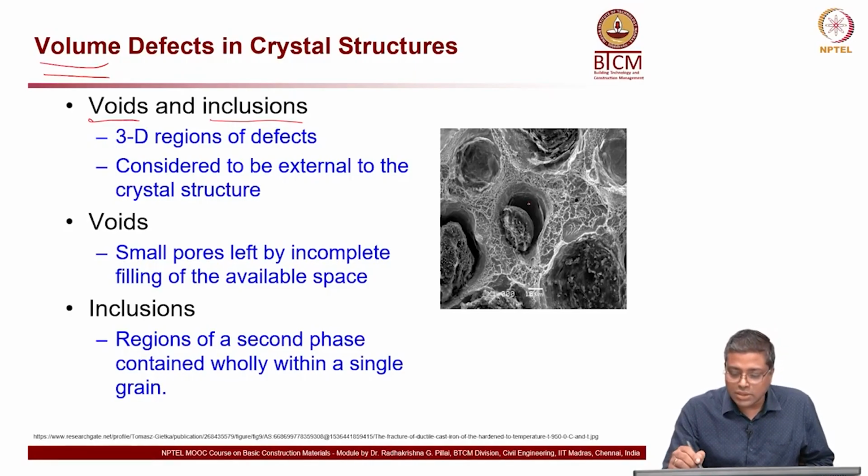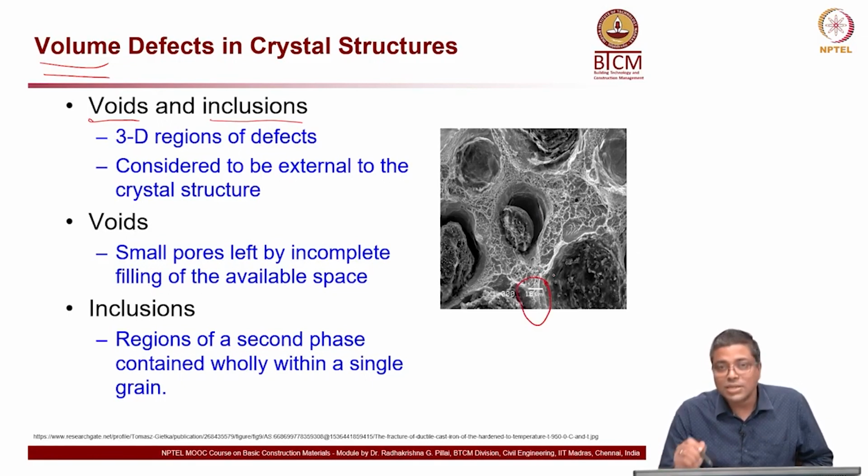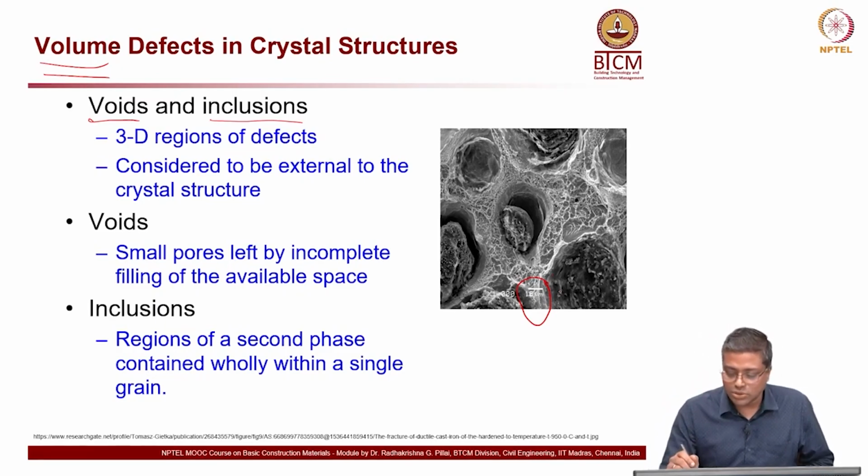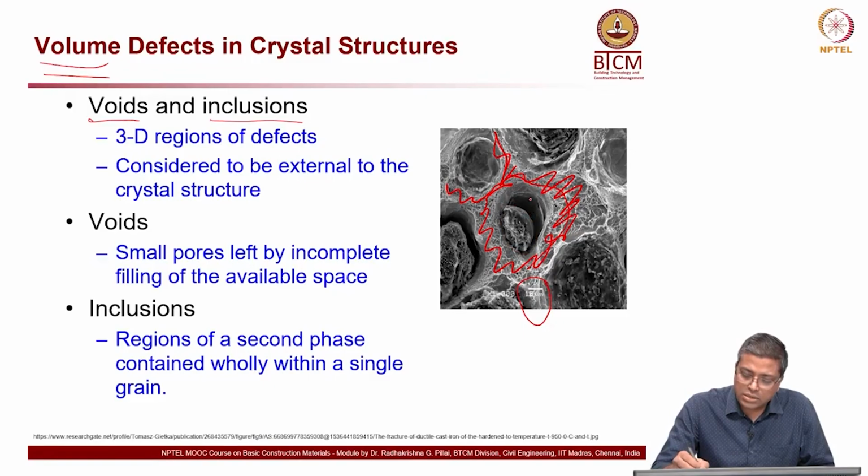Okay. So, you can see this micrograph on the right side, you can see the size over here, there is a white line, and that is 10 micron, that is 0.01 millimeters, so small, right. Now, this is what we can say is an inclusion inside a material. So, this region here is the bulk material, and this region, the center one, I can say is the inclusion.